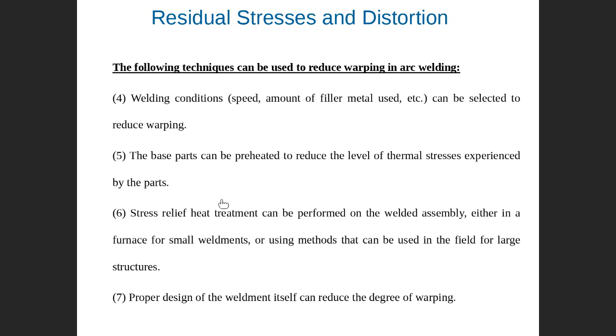Stress relief after you finish the welding. After you finish the welding, you can do stress relief by heat treatment. What is the heat treatment? You heat the weld or all the base material, you bring all the material and heat it, and when you heat up to a limit, the recrystallization limit, all this kind of residual stress will be released. This will give relief to the residual stress.